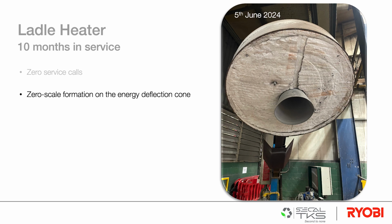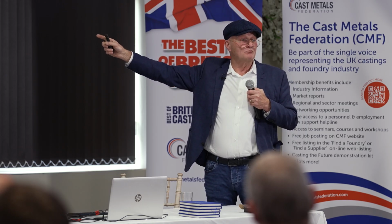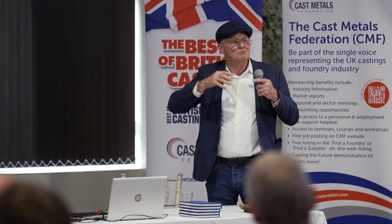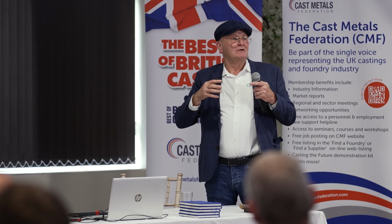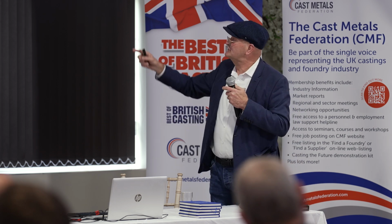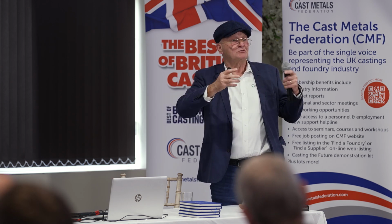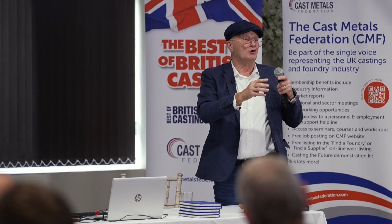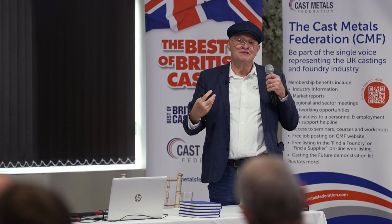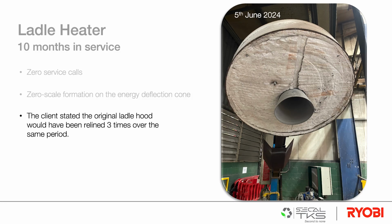But that's, I think, 1200 C blanket. It's not the top blanket, but it looks after it. And it doesn't impinge the way that the flame does. And the other thing about it is the fact that if you've got castable, every time you're switching the unit on, you're heating that castable up, as well as heating the ladle that you're trying to get the heat into. So in essence, that's basically where we are with that one.